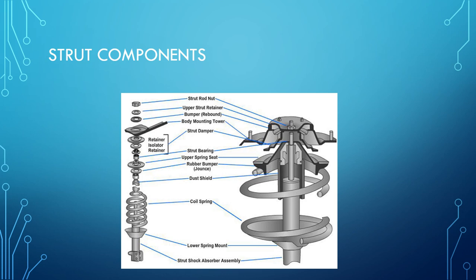And this is a good time to let you know that a lot of struts now, aftermarket applications only, to the best of my knowledge, will provide you with a complete strut replacement. In other words, instead of having to decompress the strut in a tool and then using some of the old parts to put onto the new strut assembly, this allows you to change the strut as a whole. So you take it out of the box, you mount it to the car. The idea is to save on labor time and mix and matching old with new parts.